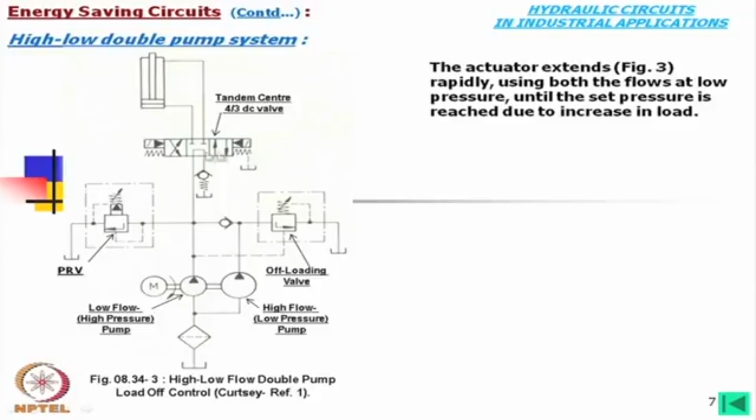And we find there is a spring. This means that if we actuate this way and then relieve the actuation load, it will go back to the neutral position due to the spring, the same for this part also. And whatever leakage there is, there is a drain, this is called the drain port.